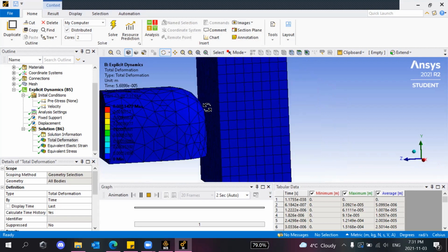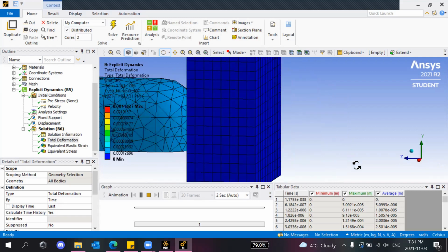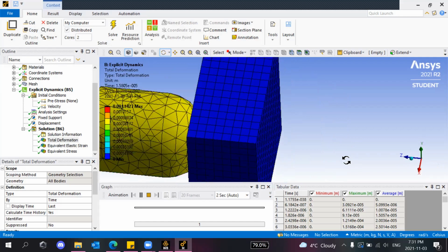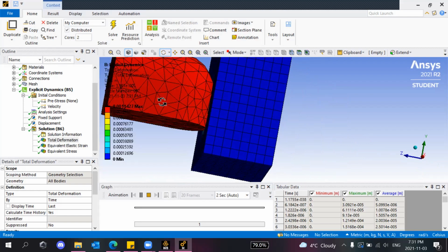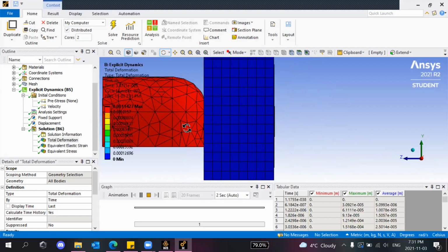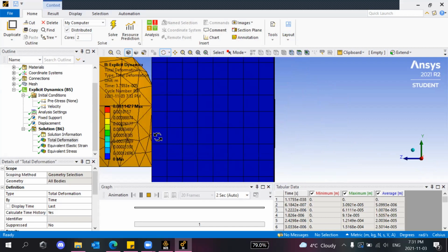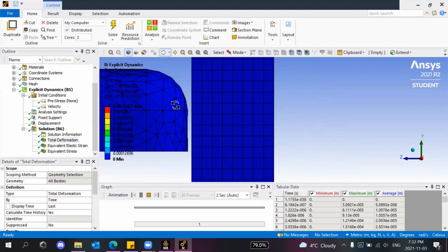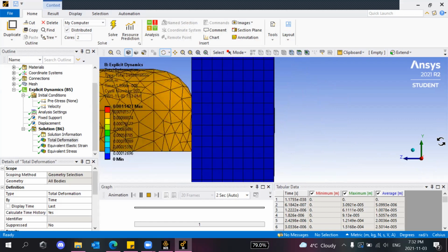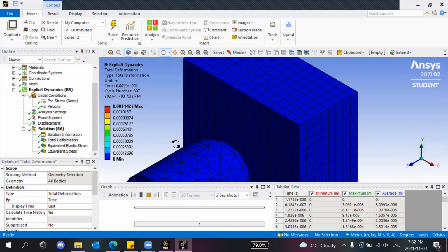So in this case, there is no plasticity data in this wooden material. That's why you can see it's bending a bit due to its elasticity. And there was also no plasticity data on the structural steel, which is why you can see the shoe also bending. I mean, it wouldn't be showing any plasticity anyways, because it's a steel toe boot, but these results, as you can see, aren't completely accurate. However, what you can still get from this are the maximum stresses that occur on the door and on the shoe.